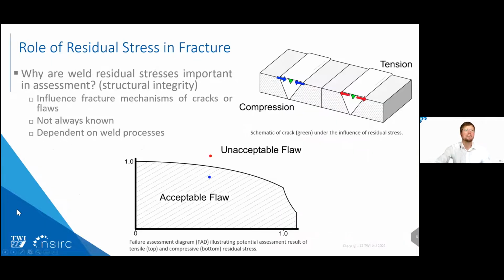So what are residual stresses and why are they important? In general, they can accelerate crack growth, and this is dependent on whether your crack is in a tensile region or a compressive region. These can change depending on the location of the crack and the weld process, and most importantly, these are not always known. You might have a weld, but you don't have a measurement for that weld, so you have to assume them in most cases.